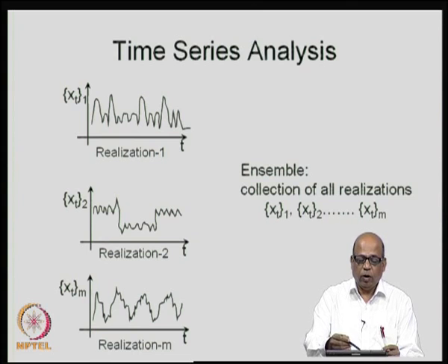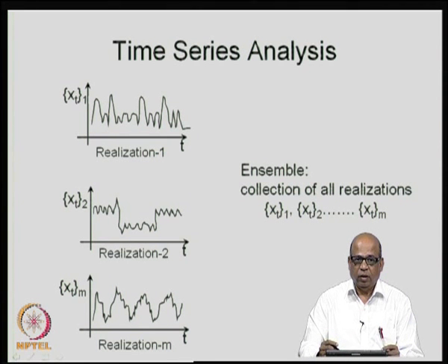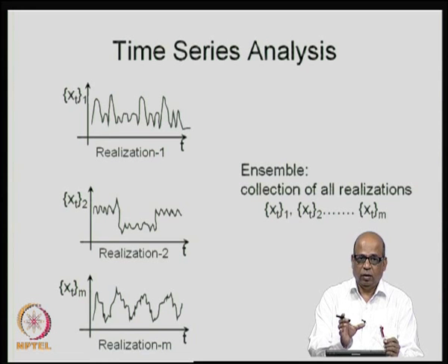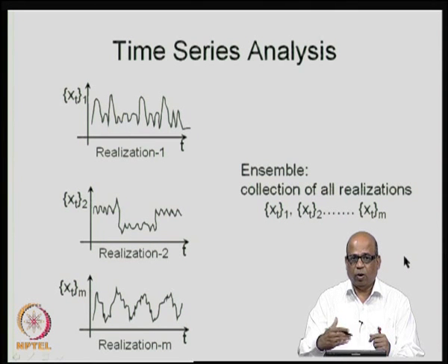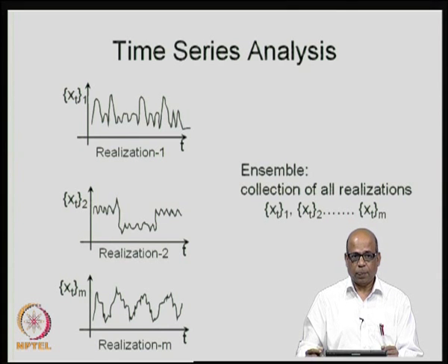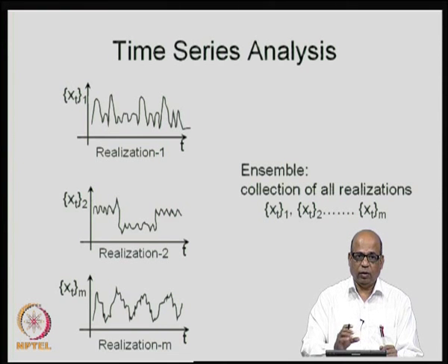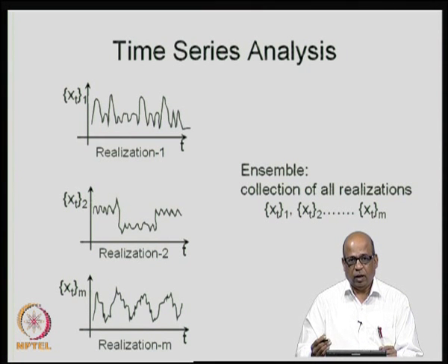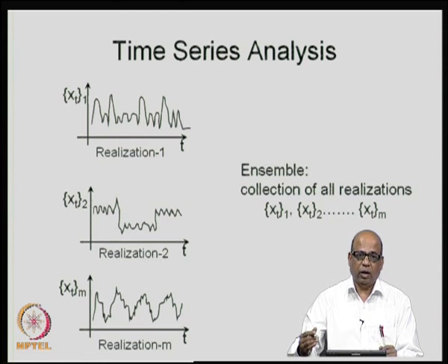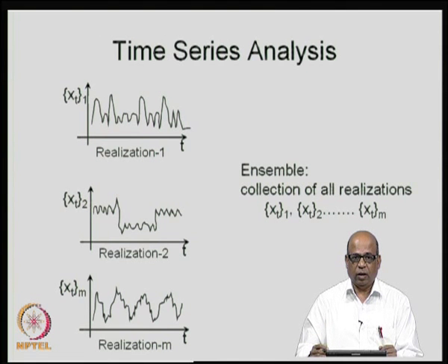But when you want to have several realizations, you can split this time series into several shorter time series, shorter realizations. Let us say you have the last 50 years, then you may split it into the first 20 years, next 20 years, last 10 years and so on. Like this, you may have several realizations just to examine how the time series is behaving across time, whether the properties have remained stationary and so on. So, you can split the time series. But however, as I said, in hydrology we are handicapped with large lengths of data. So, you may have to deal with one or maximum of two realizations in most cases.